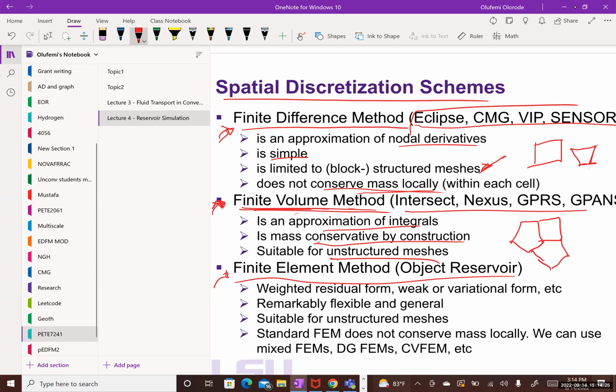And that allows you flexibility to conform to different discontinuities in your domain, like fractures, like channels, like different material interfaces that don't have to be straight lines. So that's the advantage of using unstructured meshes. Locked or structured meshes will not be able to conform. There's no way you will be able to mesh this fracture, these 2 fractures, with Cartesian grids easily, right?